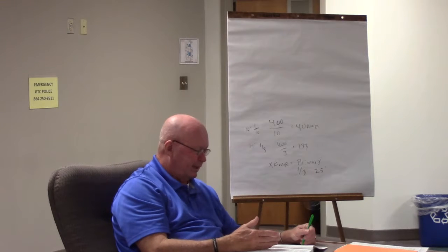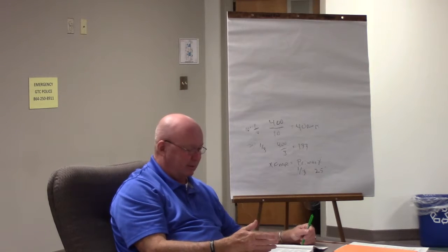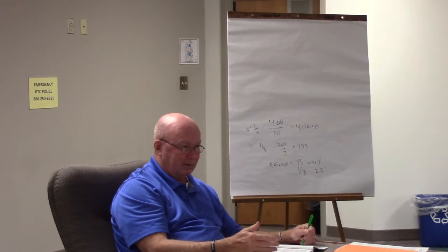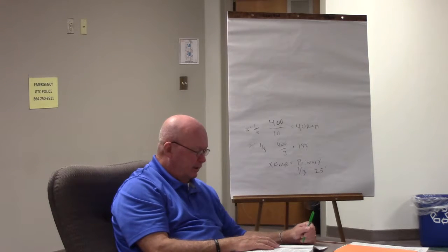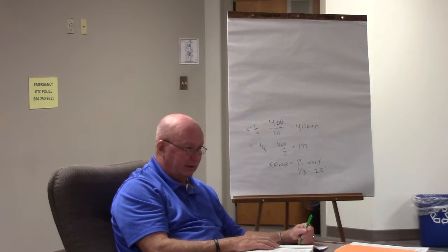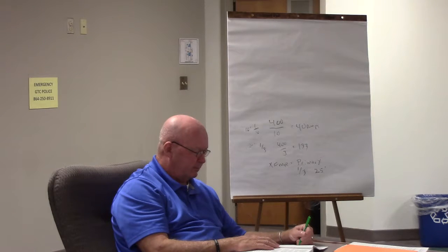Now here's something different we hadn't seen so far. Number 4 says what? The tap conductors must be what? Not displaced. Not be spliced. Okay. Number 5 is a little bit different. The tap conductors must be a minimum size of what number size copper? Number 6. Number 6. A little bit different there, isn't it?